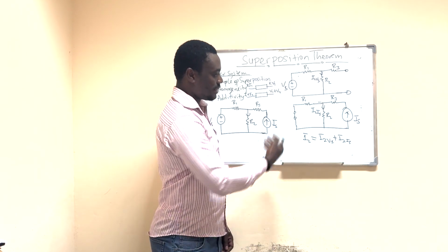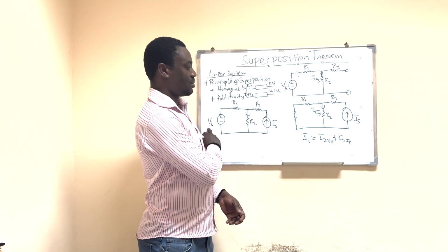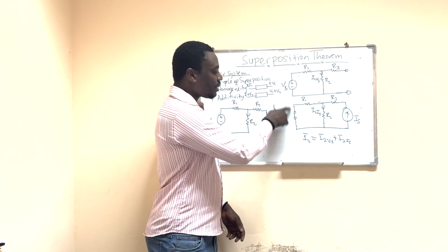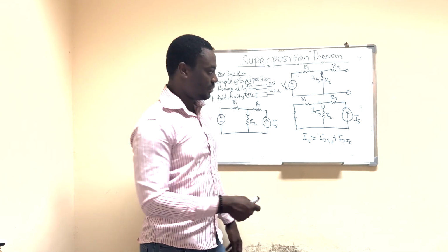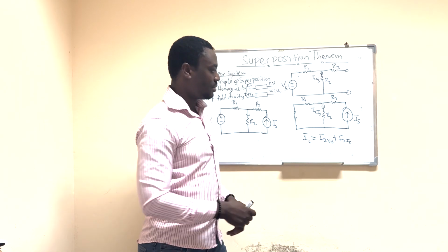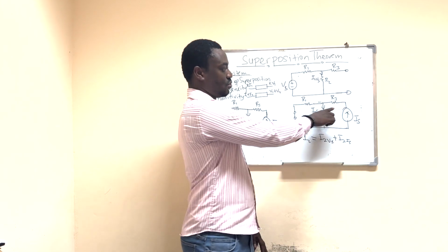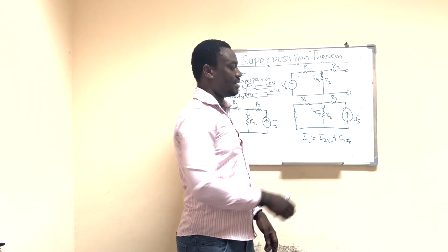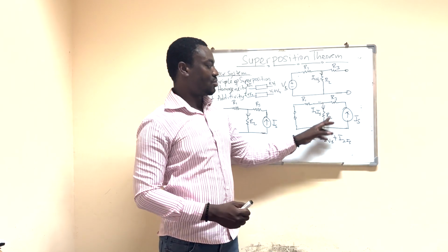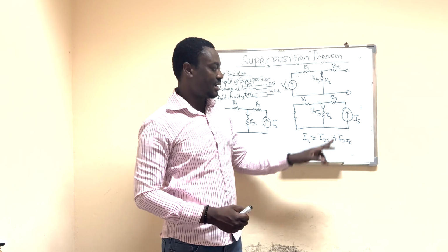Now we come to the next circuit diagram. This time we are going to turn off the voltage source by connecting a wire, meaning we short circuit the voltage. That will make sure the voltage there becomes 0. Then this time we have our current source. The current source here becomes the current passing through R3, and then it arrives here, and we have a node, right? And then we have current passing through R2, which is our interest. We're interested in that current.